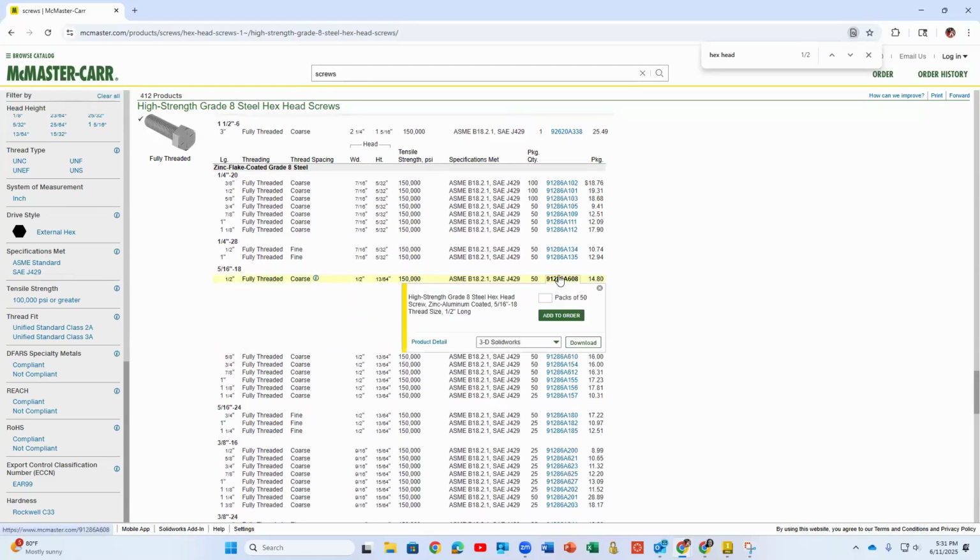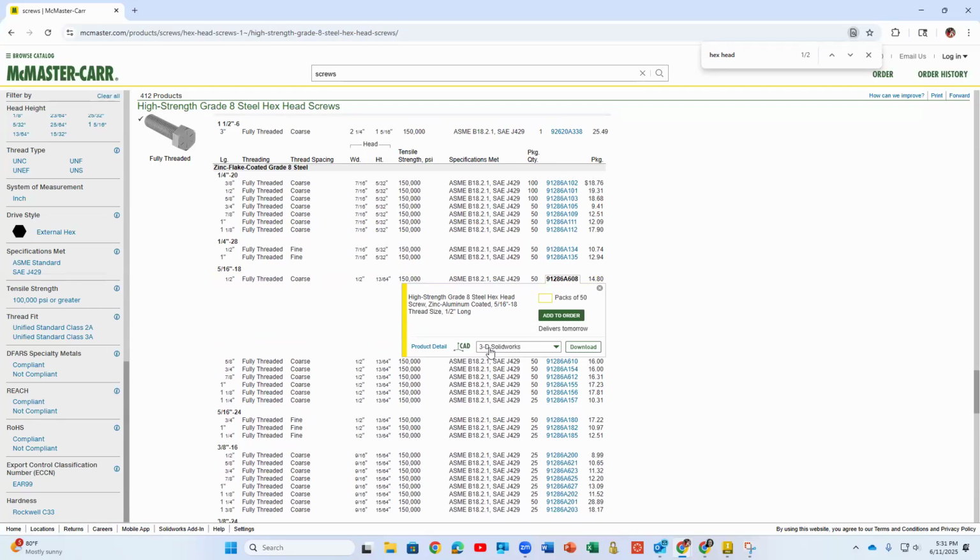So for example, if you want to buy it, you go there, and if you want to get the CAD drawing of it, you would select your part and get, for example, some of these. I'm not seeing the Inventor one, but some of these are just generic ones. DXF will be more of a 2D drawing, but if you want a 3D model, you might try a neutral one like STEP or IGES. So let's see which ones they are telling us. We can get some of these, and we can get our part.